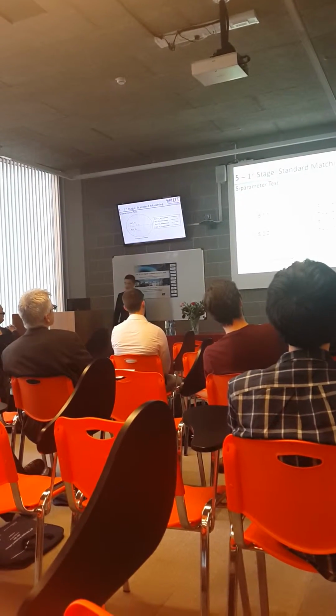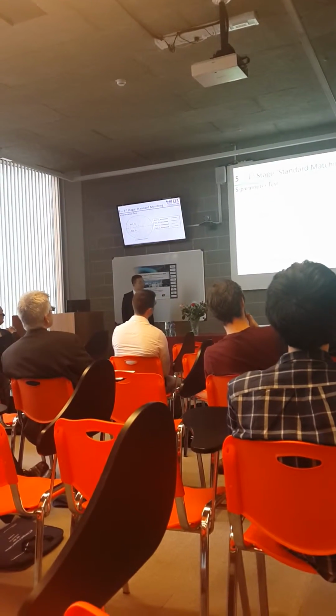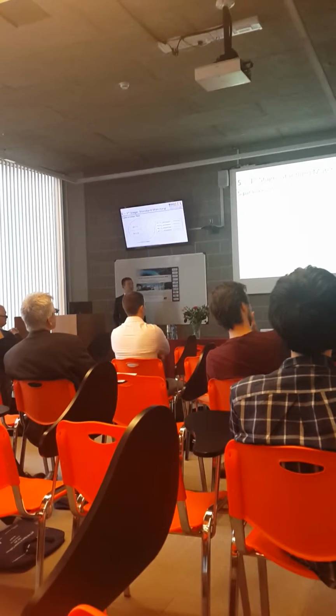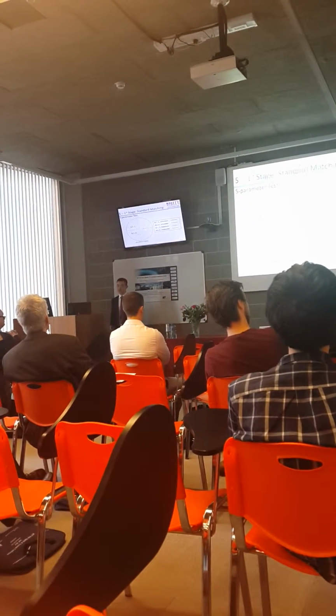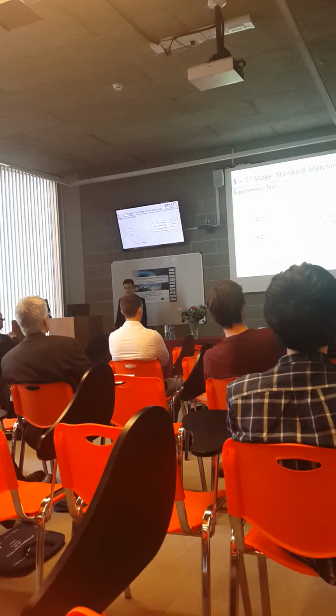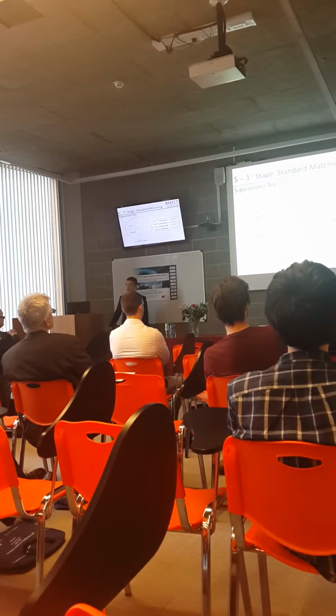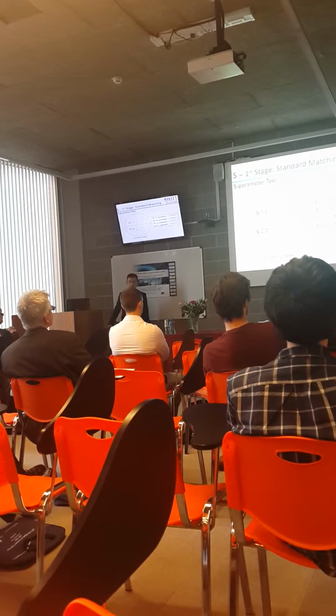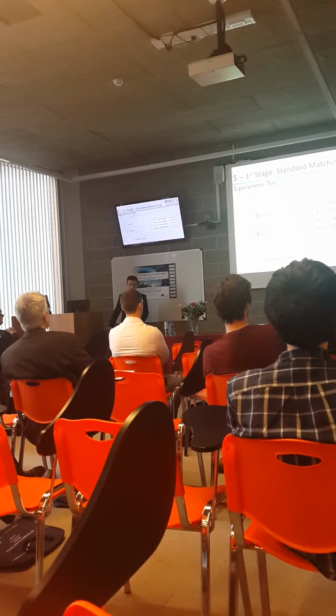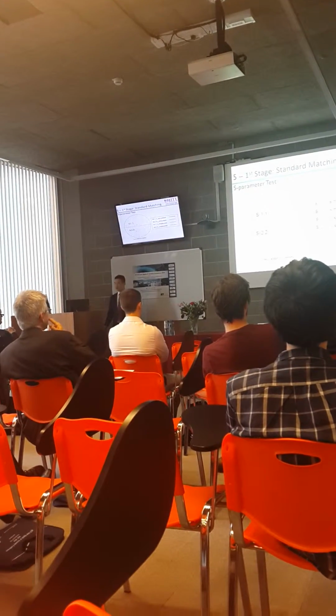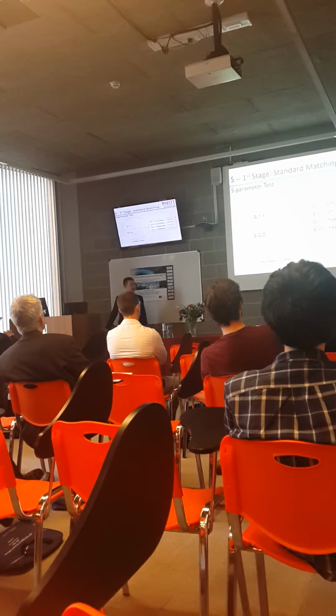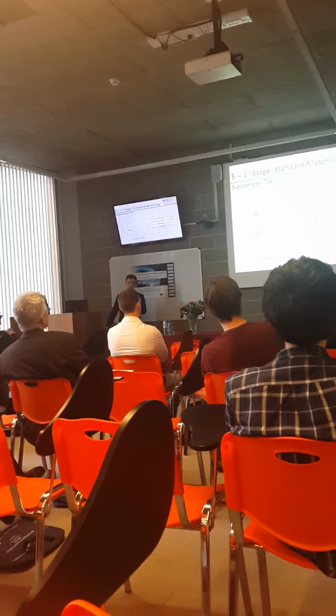For the first stage, standard matching, as you can see from the Smith chart, basically the idea is to get into the center of the Smith chart to give you a better result. As you can see, we aim for the low power consumption for a low noise amplifier. That way we sacrifice a little bit for S22, which is considered the gain part.